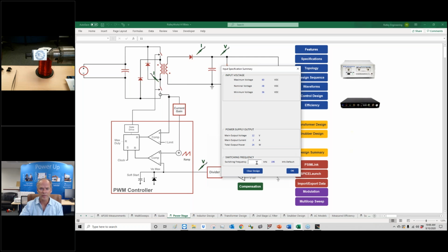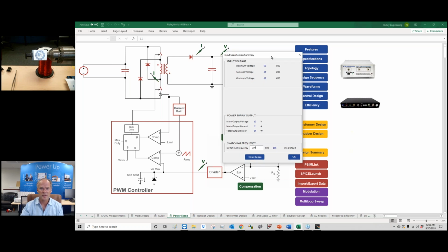And we're going to up the frequency here to 200 kilohertz. As is a funny industry, we've been designing flyback converters at 100 kilohertz for about 40 years now. And despite all the talk of higher frequency switches, GaN, and all the rest of it, everybody still designs their flyback converters around 100 kilohertz. Lots of reasons why they do that, but you'll be surprised the advantages you get once you start raising these frequencies. Going to 200, 300, 500, whatever value you want to use, experiment with trying high frequencies. That's what we're doing here.